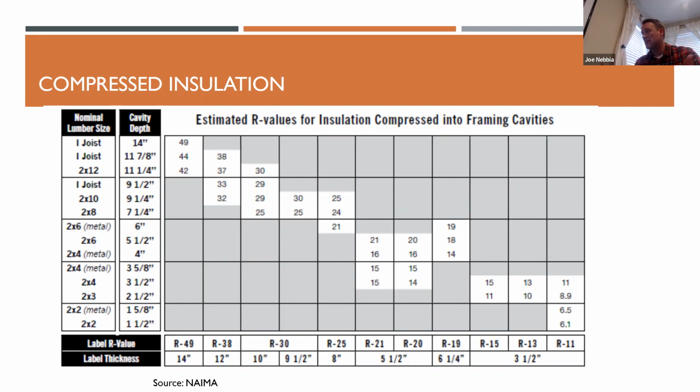because when you have something like fiberglass, the air pockets in that material are an important part of the insulating factor. And when you compress the insulation, those disappear. And so you get less R value out of it. If you're at a batt that's 6 3/4 inch, you might be down to an R17 when it's compressed into a 2x6 wall. So something to keep in mind for your installation. The material does matter, and where you're putting it is going to matter.